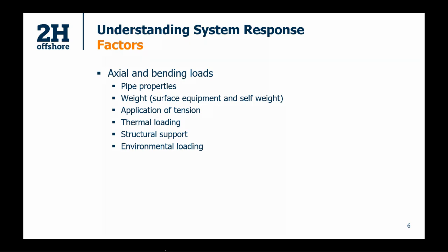So if you're looking at a system that is in drilling operations, a system that is in production or in injection, the thermal loads that you associate with production and injection mean that you're looking at very different axial states in your conductor during those operations. You also need to understand the structural support that the conductor has. So what lateral support does it receive? It guides and decks from the platform structure. And then finally, the environmental loading. Obviously, that's not one that we can control, but it is one that has a significant effect on the response of the system.